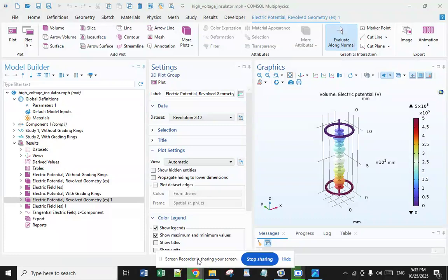Maintenance of earthing insulators includes regular visual inspections for damage or deterioration, as well as insulation resistance tests to verify their effectiveness. Periodic testing is essential to ensure that the grounding system remains capable of effectively handling fault currents.